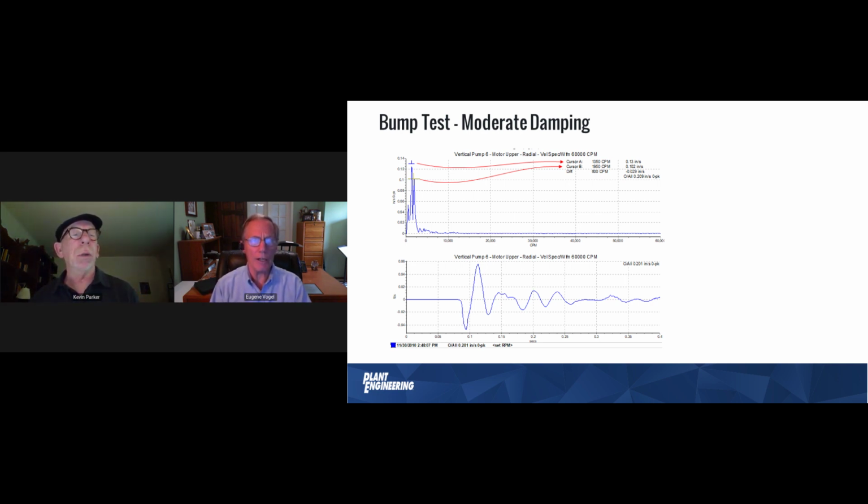One idea is that I don't want to transfer the vibration from this machine, whatever it might be, to the rest of the structure. I want to isolate the two. And the springs allow the machine to vibrate all by itself without any of that vibration going down to the other side of the springs. So isolation is one reason, to keep it from transmitting that vibration from one to the other.